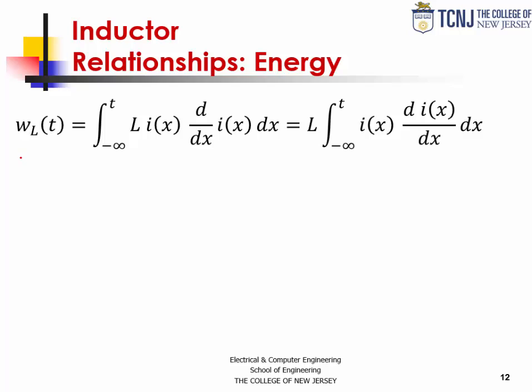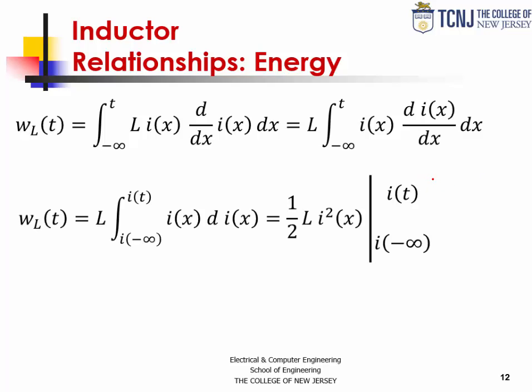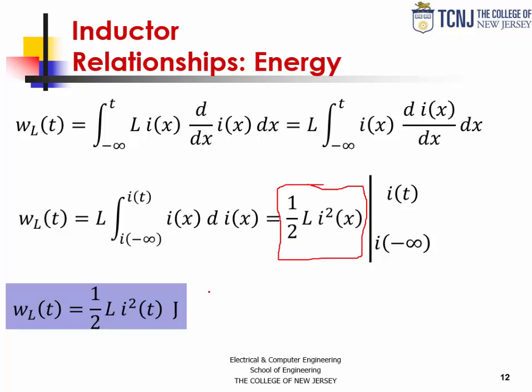Energy is also important in an inductor. How much energy is an inductor storing? That is the integral of the power expression. So we can integrate from minus infinity to time t the power expression, and we get this expression all the way to the right. We can simplify that, and similarly we get a very nice closed expression for the energy stored for an inductor, which is this one over here.